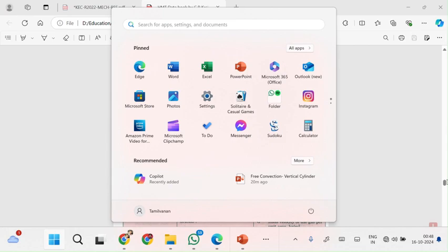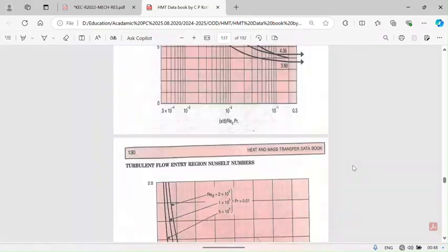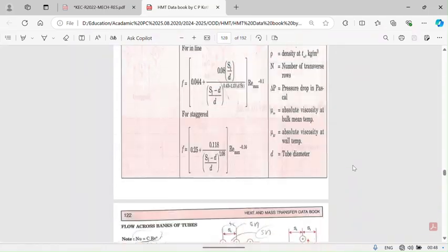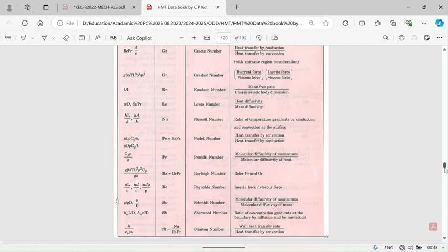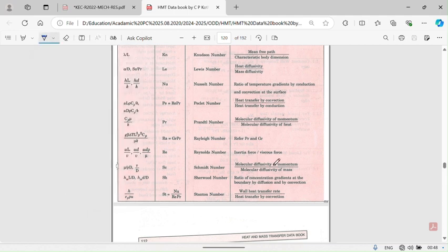So here, PR can be calculated by means of a formula. The Prandtl number is equal to the ratio of specific heat Cp times mu divided by K. In the problem, the thermal conductivity is given. The absolute viscosity mu is not given, but you can calculate mu directly from the density and kinematic viscosity. K is given. So instead of mu, we can substitute rho times nu.